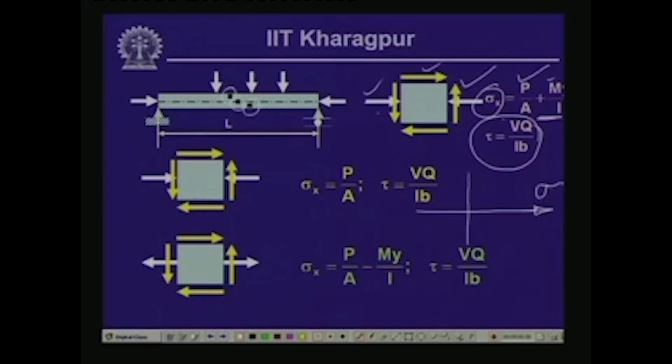As you know, this is the sigma axis and this is the tau positive direction. Now, here if you plot the values of the normal stress and the shearing stress as we are computing from these formulae, and since you do not have any sigma y, so sigma y and tau, and if you join these two points together, you get the circle, and thereby this gives you the maximum value of the normal stress, which we call sigma 1 or the principal stress. In fact, this is the answer for the second question as well.